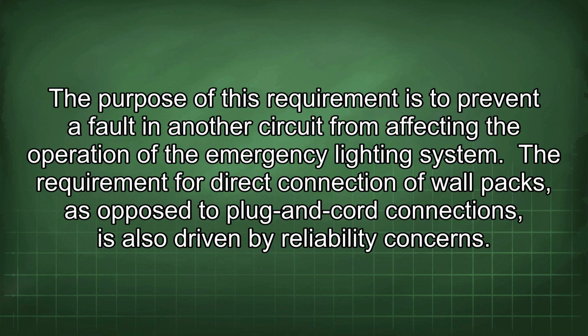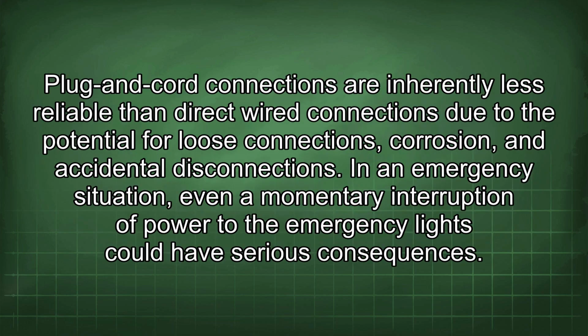The requirement for direct connection of wall packs, as opposed to plug-and-cord connections, is also driven by reliability concerns. Plug-and-cord connections are inherently less reliable than direct wired connections due to the potential for loose connections, corrosion, and accidental disconnections. In an emergency situation, even a momentary interruption of power to the emergency lights could have serious consequences.